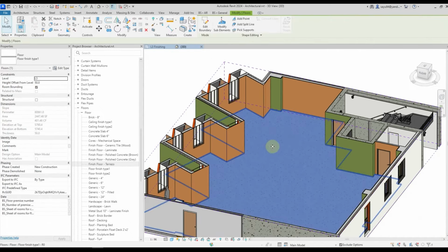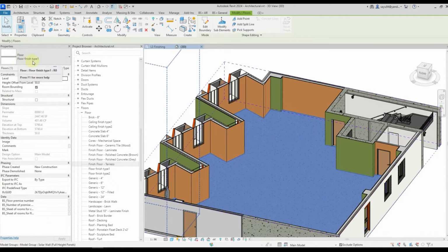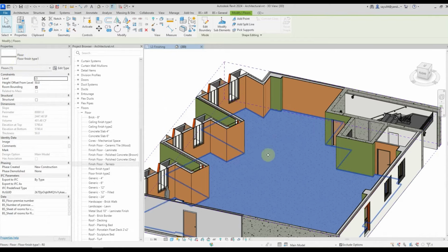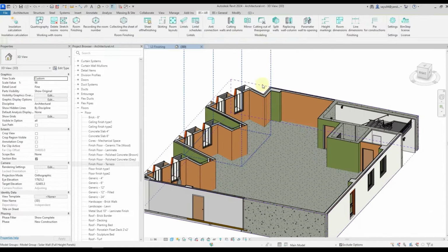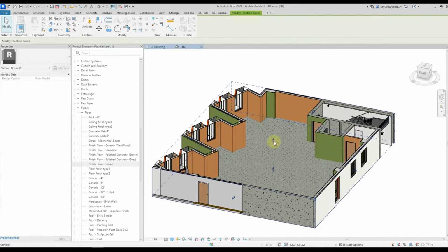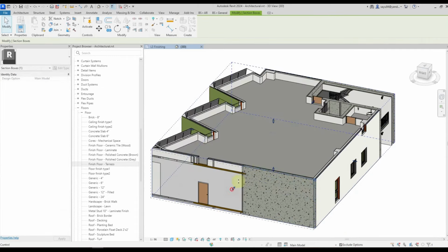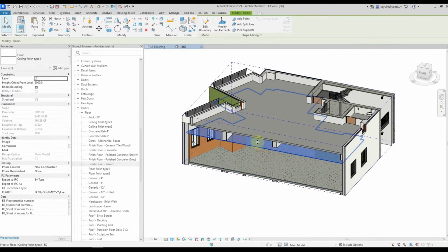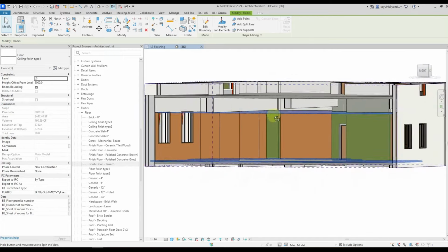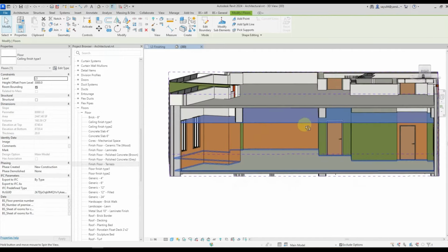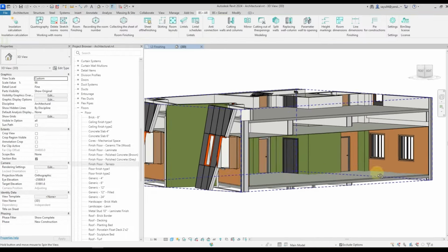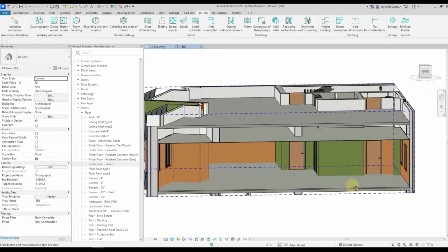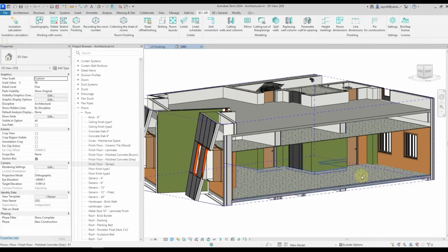Same thing with the floors. We had modeled a floor that's called type 1, and we have it all over the room. Same thing with the ceiling. Let's bring finishing boundary up, and we'll see that the ceiling was made like the floor, which is 3 meters high, and it's type 1. So we have modeled the finish throughout our entire room depending on the type of elements being finished.